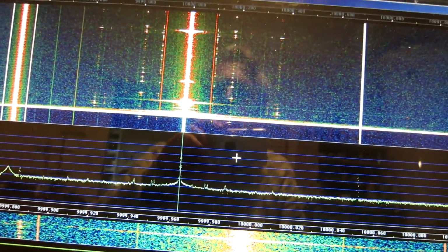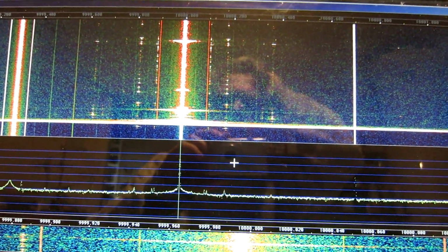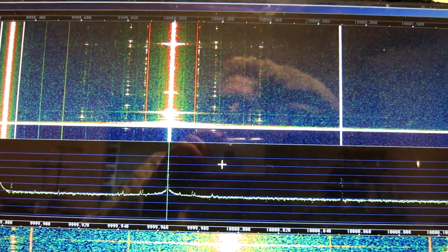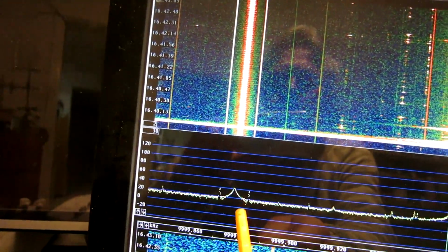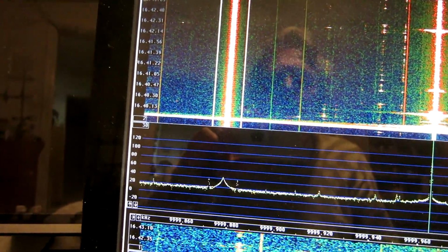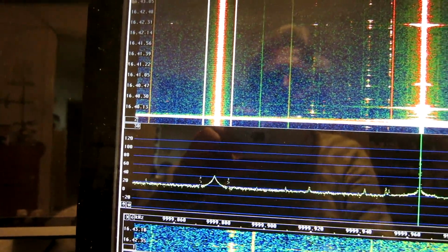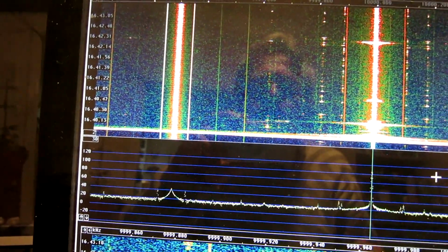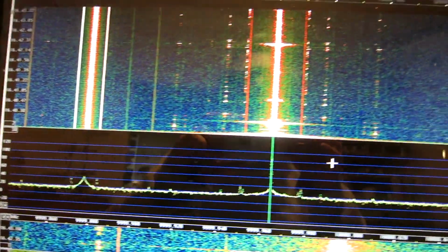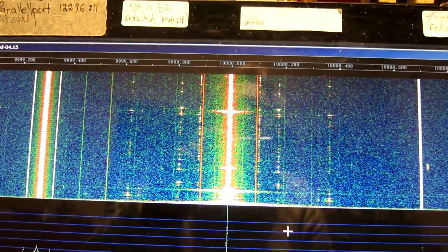It means that what I see is correlated between the channels. This peak here is the noise at DC for the sound card, so that is of no concern. And these lines are the 50 Hz going into the sound card. And this is when I adjusted the interferometer.